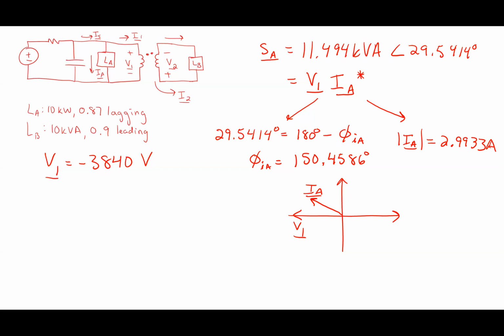Supplying voltage. It's supplying voltage. What do you mean? In the same way, negative power. No, it's absorbing power. What you're saying is the voltage across it, if I really drew it properly, the plus minus on V1 should have been reversed. And I actually do have a current going into the true plus sign of that. So it is absorbing power. Don't worry your head too much about that. I'm happy to talk with you more about that one.